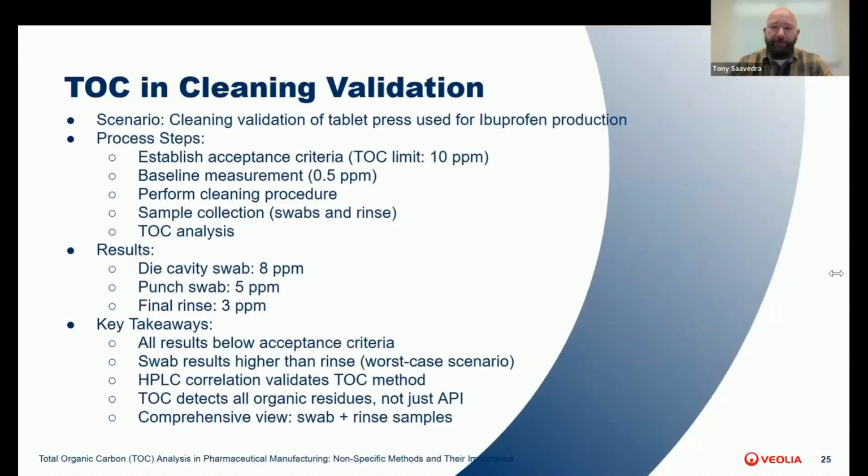Now, in practice, we repeat this process multiple times to ensure it's reproducible. We'd also challenge our process by intentionally dirtying the equipment to prove our cleaning can handle the worst case scenarios. This example, I believe, really shows how TOC can give us a quick, comprehensive check of the cleaning effectiveness. It's sensitive enough to catch low levels of residue, but broad enough to pick up unexpected contaminants that a specific method might miss.